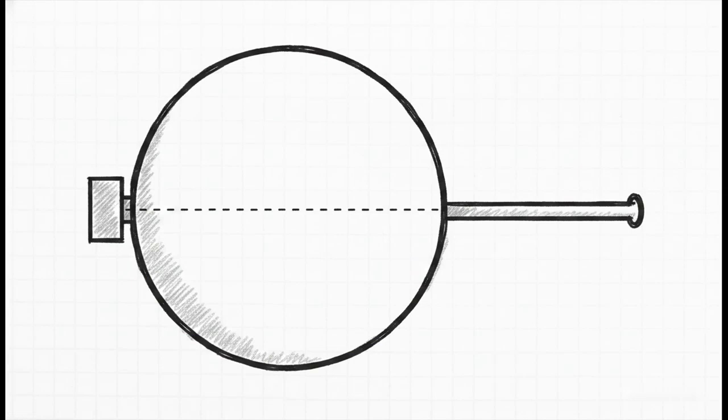So, once the manholes claim their 30-degree segment, we have to route the pipes. Let me introduce you to the 180-degree routing rule. If a pipeline has valves or instruments, it obviously needs to be near a platform so a human operator can actually reach it. But if a line is just a straight run of pipe heading straight out to the yard or a pipe rack, designers optimize the whole layout by placing it on the 180-degree segment. That's the complete opposite side of the tower, as far away from the manhole platforms as physically possible.